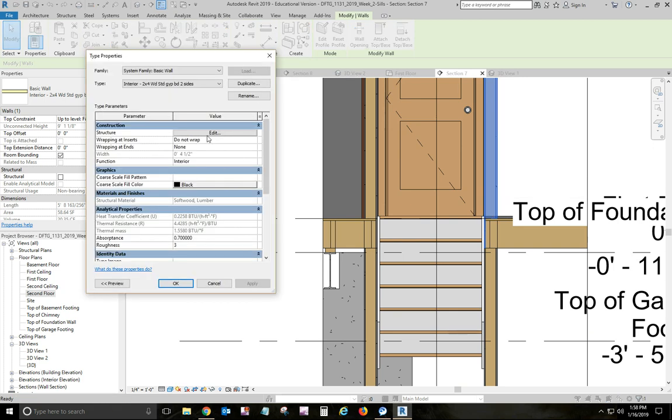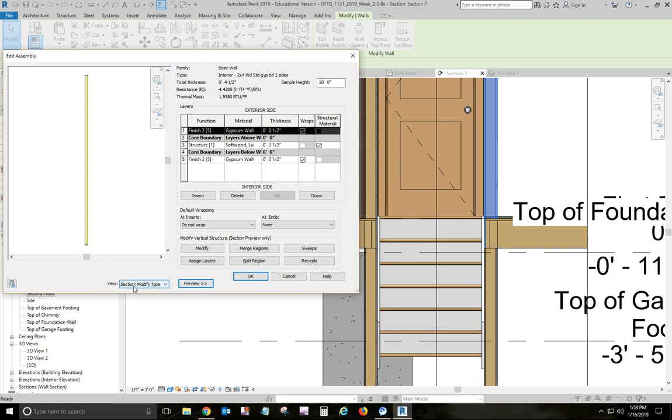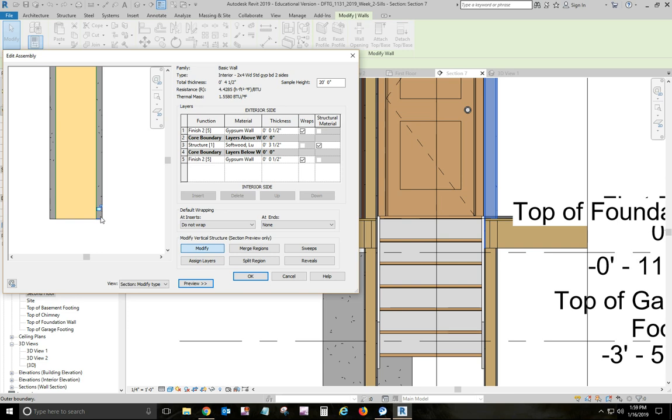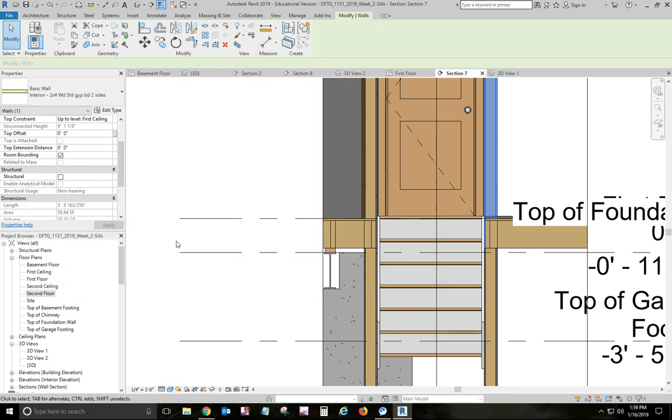and go edit the structure. And what I did, I'm trying this in that I made like one side of the bottom of the wall adjustable, because you can only make one side adjustable for the drywall. So I unlocked, like say on this one, I unlocked the right side at the bottom, and then I unlocked the left side at the top. So depending upon where the wall's located at, hopefully I could adjust something, all right?